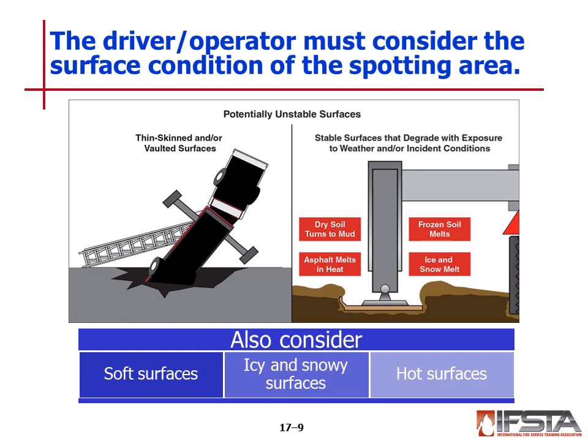A thin surface may not provide a stable enough base for apparatus stabilizers. If stabilizer pads or cribbing are not placed underneath the stabilizer shoe, stabilizers may puncture parking lot surfaces, causing the truck to sink and possibly even tip over when the aerial device is operated to the side of the truck.